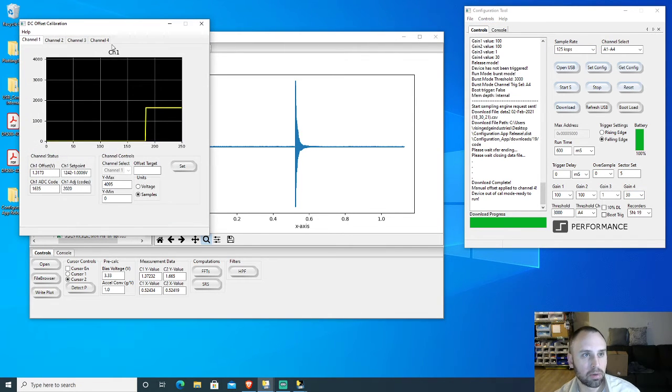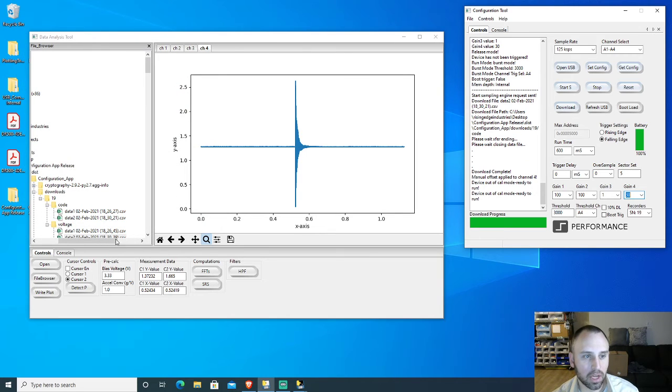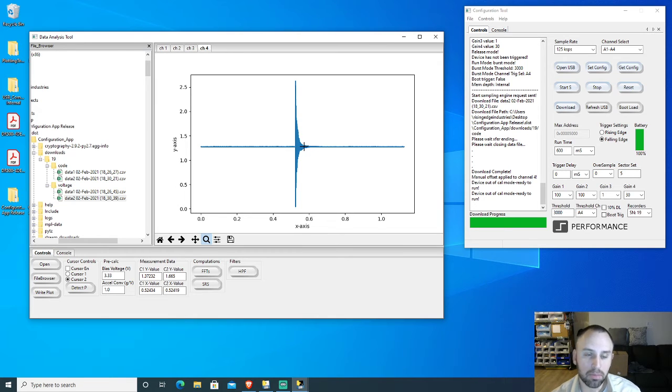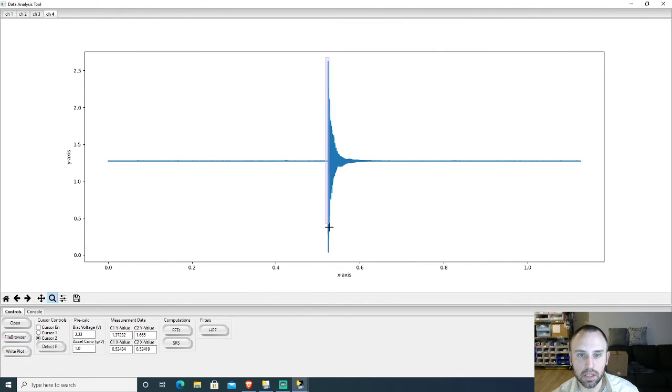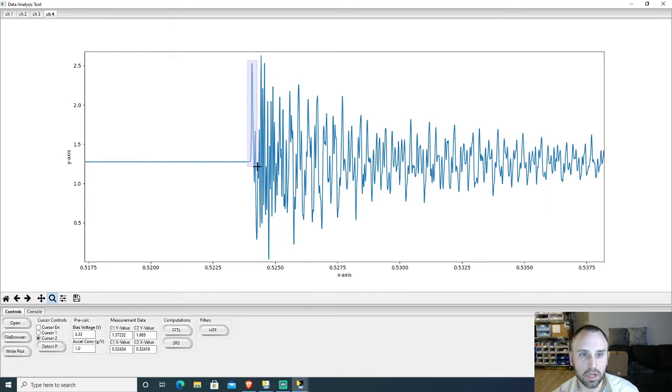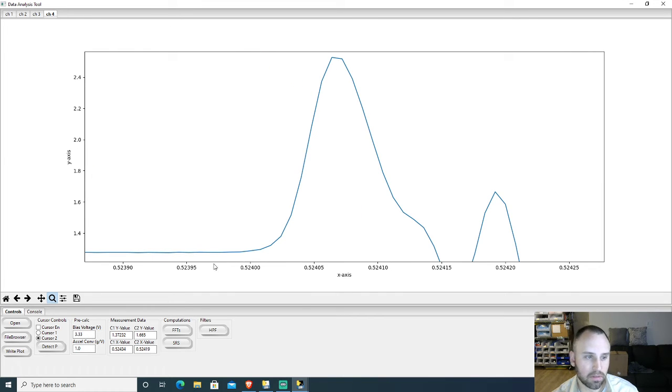So to solve that clipping problem, all we did was go in here, set a new target to move the DC bias of the channel 4 analog channel up a little bit, and reset the recorder, and we were ready to capture a new waveform. And this was all captured in burst mode, so the recorder was running fairly autonomously. It's just set up, click start, and then once it saw channel 4, which it was set up to monitor, exceed our voltage threshold on this first pulse here, it triggers itself.